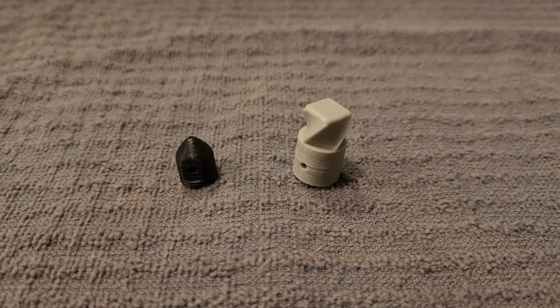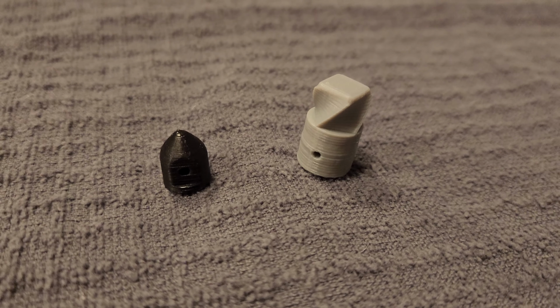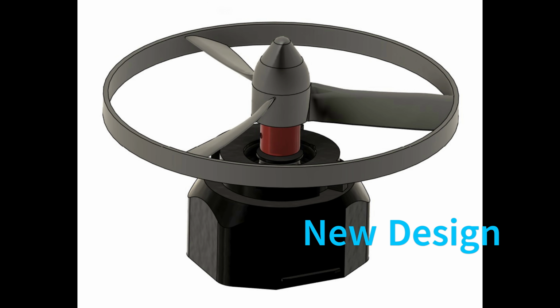The old design relied on a trigger system and the new one relies on a helical corkscrew system. The old design was a lot more complex, requiring multiple parts to hold the propeller in place, including a bearing mounted on the propeller, increasing its mass. The new design requires no parts whatsoever except the connector itself and is a lot more simple.